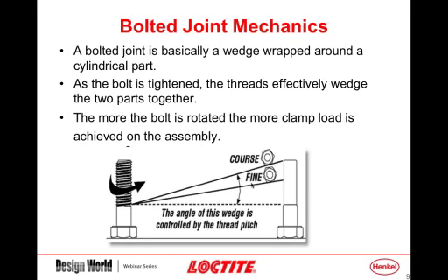if you were to take a fastener and unwind the thread on the fastener, and here I have two examples of a coarse and a fine thread, where we've essentially just stripped out the thread, you can see that it is really nothing more than just a simple ramp. And on a coarse thread, which would typically have 16 threads per inch, this ramp is about a 3-degree ramp.